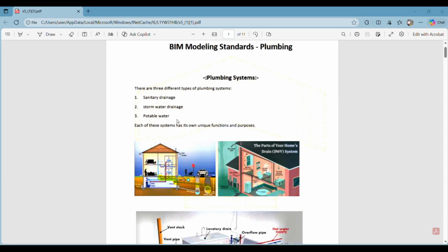And then we have the next system called the stormwater drainage system, or stormwater management system. It is used for handling rainwater and preventing floods, waterlogging and structural damage. Can you see here on our roof we may get some rain and some runoff from this roof. So this stormwater system manages all the water that we get from our roofs, and it prevents flooding and waterlogging, and it safely transmits this water into the stormwater drainage.